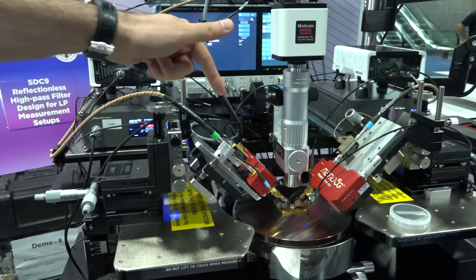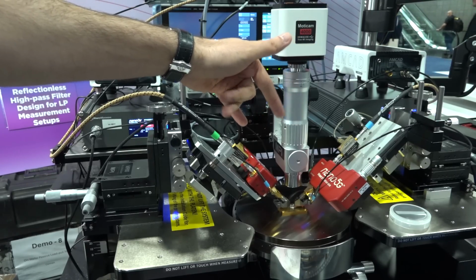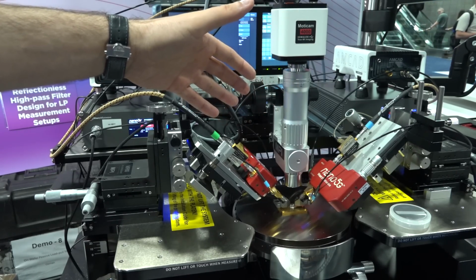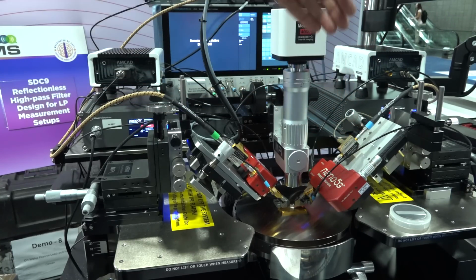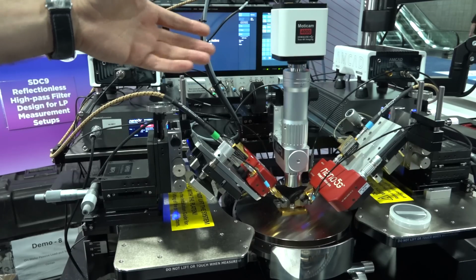The interesting configuration here is that you do have these 2 tuners directly as close as possible to the probe, so you do get 0.85 coverage on the Smith chart in passive mode, and then you do have the active terminal directly connected, and once you have the active terminal, you can inject your own signal, and then of course you can do anything you want. Then you would be in the active load pull region.